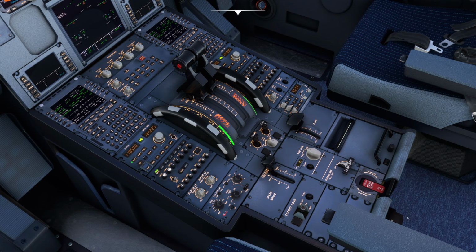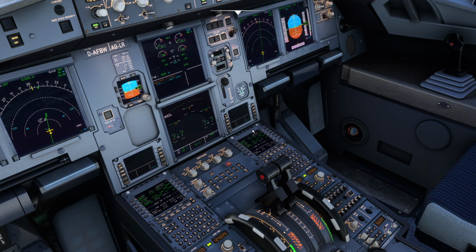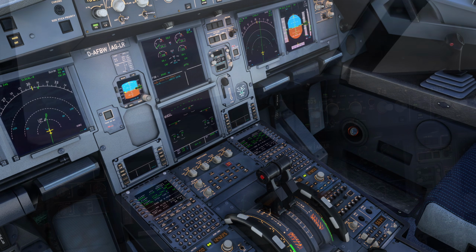The point being, if you lose electrical or hydraulic control of the landing gear, we can still lower it with this gravity extension. We are just using the weight of the wheels, and they are heavy things, to lower themselves into the airflow. So to do this, what are we going to have to actually do? Well, let me run through it with you now.